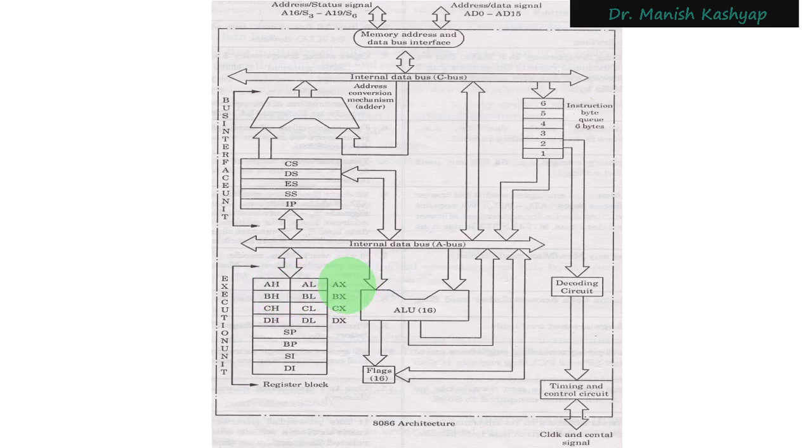I mean, in 8085, if you see the subtraction command, one operand was fixed to be the A register, and the other could be anything else. It could be data or another 8-bit register. However, in the subtraction command here there will be two parts on which it will operate, and none of them will by default be considered as AX. So that is also one point of difference. But still, we call this the accumulator register. It is of 16 bits, and this is the primary reason why this 8086 microprocessor is a 16-bit microprocessor.